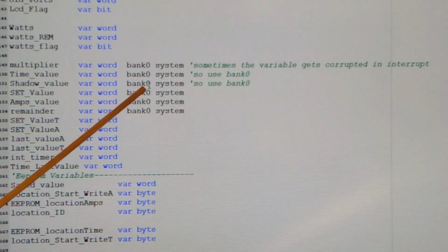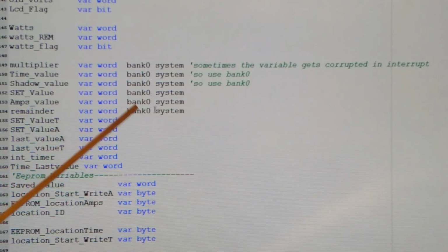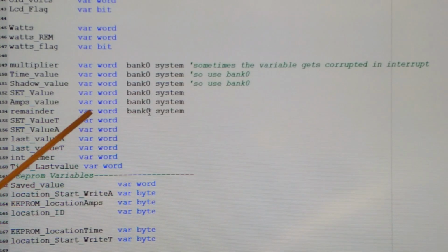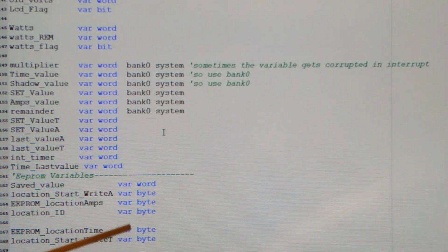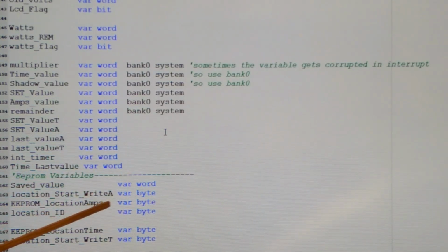Normally when you go to an interrupt, this bank doesn't get corrupted, and that's why any variables that you want to keep, that you're not going to be resetting while your code is working, it is advised to store them in different banks, like bank 0. So that's what that is. I actually don't need that in there because I'm not using the assembly interrupt system.